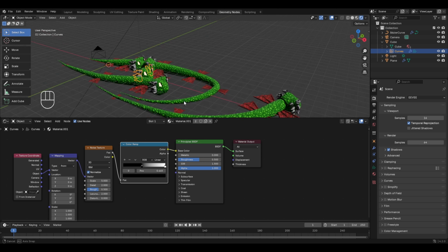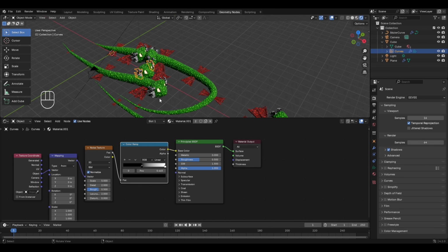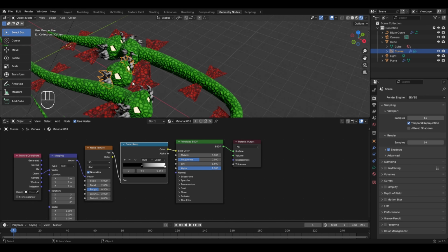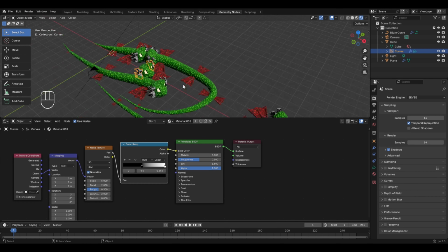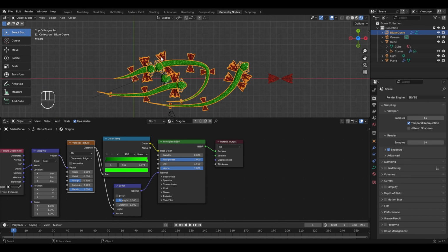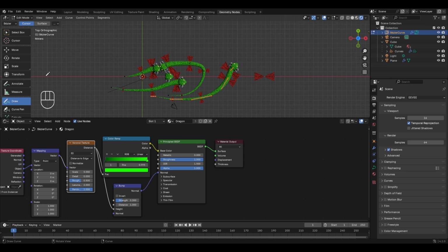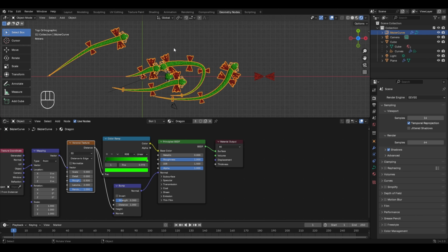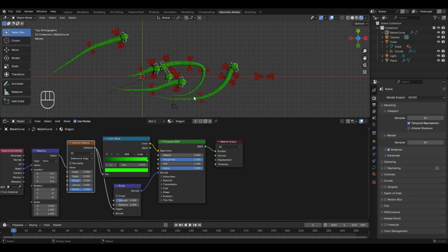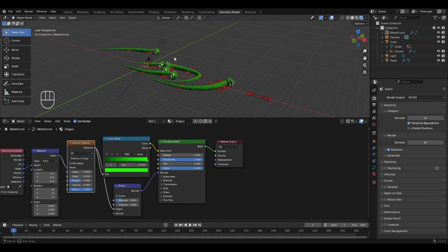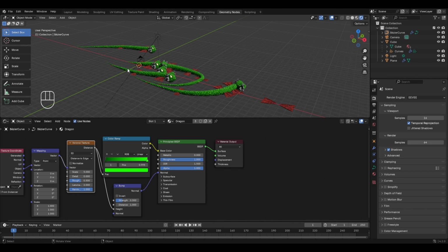In today's chapter, we learnt about some new geometry nodes, created some amazing dragons, then we even understood about the hair nodes which we use for creating these spikes. We even created these wings and also created these amazing textures. And the best part about using geometry nodes is that if I select these dragons and tab into the edit mode, then with the draw tool enabled, if I draw a curve like this, then I can easily make a dragon out of it. So try to play around with these things, try to give some more details to the geometry of the wings or the head of the dragon, or maybe you can try to give some different colors to the dragon, and in this way you will be able to create a scene of your own.